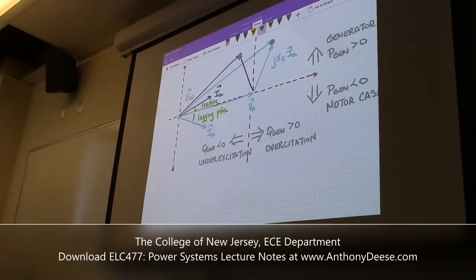What we'll see is that the work we're doing here is great for understanding the way that a generator operates, but it doesn't really translate over to trying to solve an entire system. So that's the lesson. This chapter is focused on the generator, on the synchronous machine. So we're learning about it and assuming that the rest of the world, not that it doesn't exist, but we're using the infinite bus to act as an aggregate of the rest of the power system. So there's a lot of assumptions still that we're using in this.